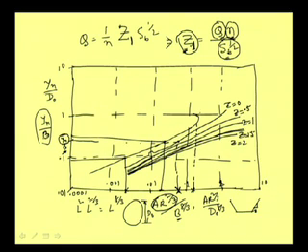But when you go to a very high value of z, that means your Q value is increasing, and then your z1 value, the section factor value, is increasing, you come to a point at this portion of the non-dimensional section factor, this divided by b to the power 8 by 3, and then your problem arises, because in this curve you have 2 points.